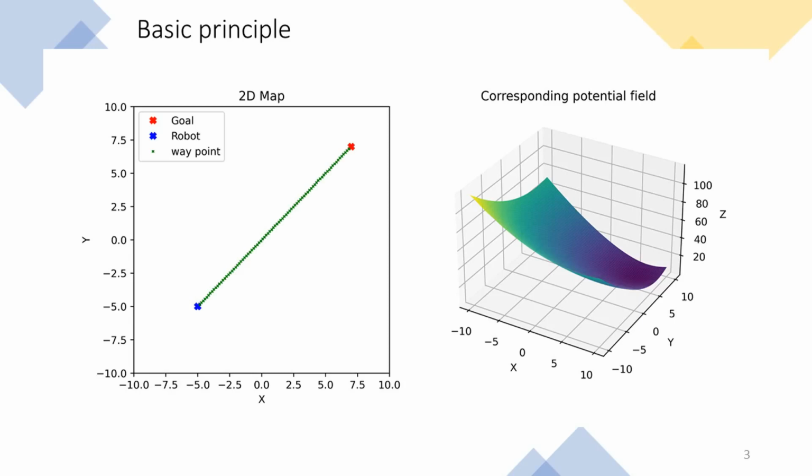So let's make things more interesting by adding two obstacles. In this case, to keep it simple, the obstacles are just 2 points. Currently, we think of our robot as a point too. To take its dimensions into account, we could for example add half of the largest dimension of our robot to the obstacles and keep using this dot representation. As you can see, we will add obstacles by adding high potentials at their position to the potential field.